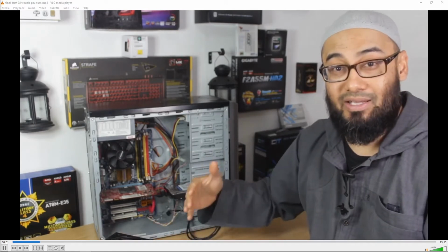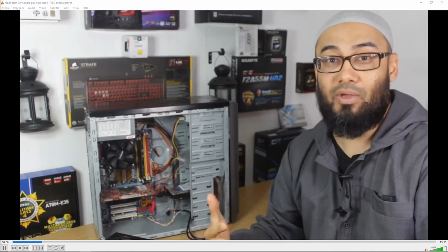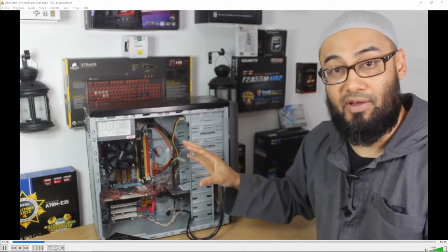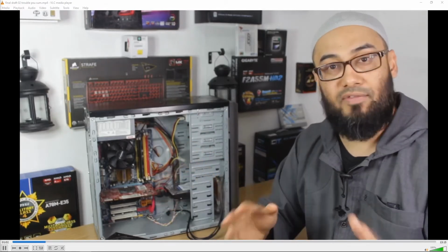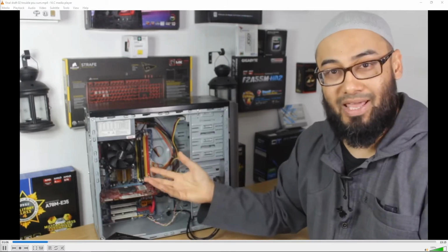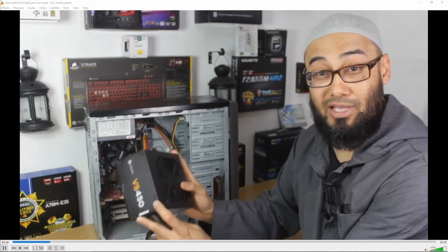2, how easily accessible is the front panel or even the power supply? 3, how quickly you can actually do each test? And 4, the actual history of the device just before you had the problem. If it's your own device and you know it was working fine the day before, in the middle of an application you had a bang, most likely it's going to be the power supply. You're going to have to test that first.